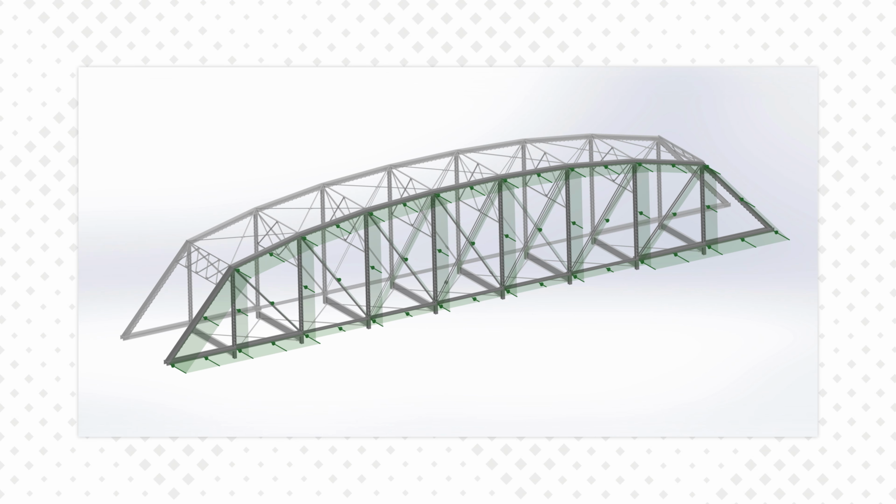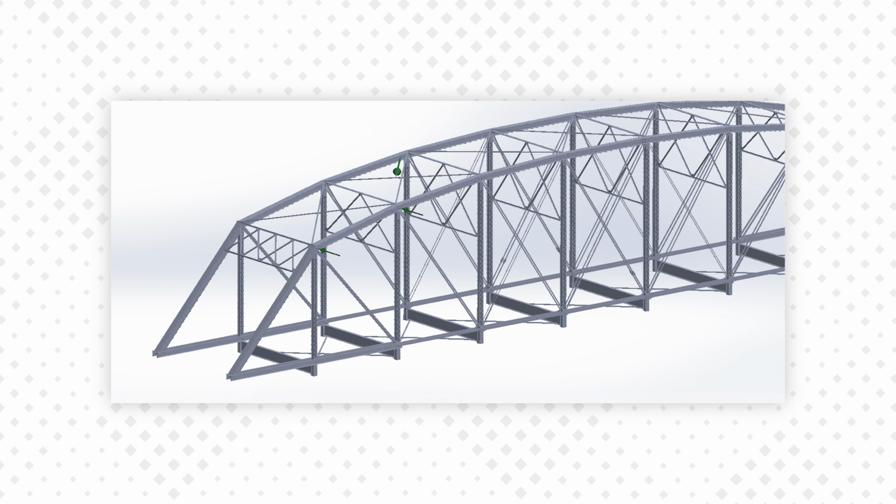Turning our attention to lateral loads, let's consider how wind loads in the Van Buren Bridge work their way to the bearings. As wind flows across the bridge, it applies a higher pressure on the windward side of the bridge and a lower pressure on the leeward side. These loads work their way to the panel points by bending the members they act on. They then enter the horizontal truss members in the top and bottom chords. On the bottom level, the wind forces work their way directly into the bridge abutments, where the bridge concrete pier pushes back against the wind.